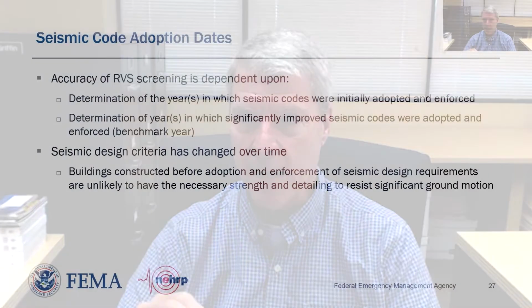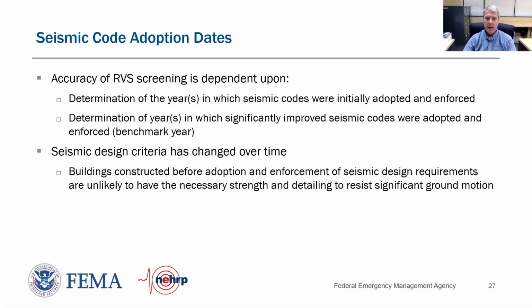And so they're not reflective of our basic score. And so we modify our basic score because of that. So that's below our average. Now, the other side of it is, okay, hey, we have buildings that have been designed 2, 3, 5 years ago to the latest building code, IBC, and the seismic provisions incorporated therein. They should have a better performance than this average level of building design of the 1990s. And sure enough, they do. And so if we have that condition, we can modify our score to account for it.